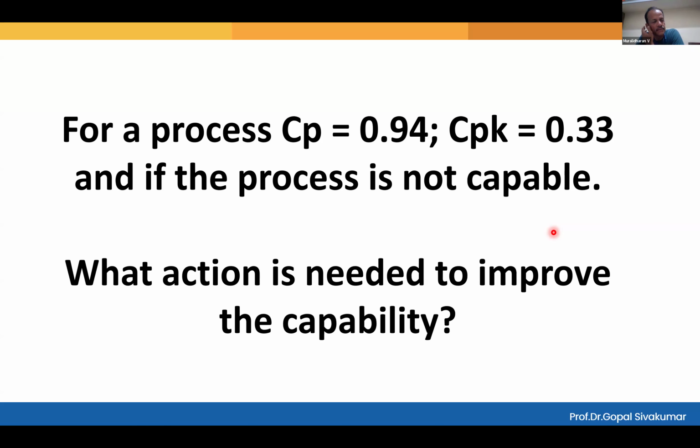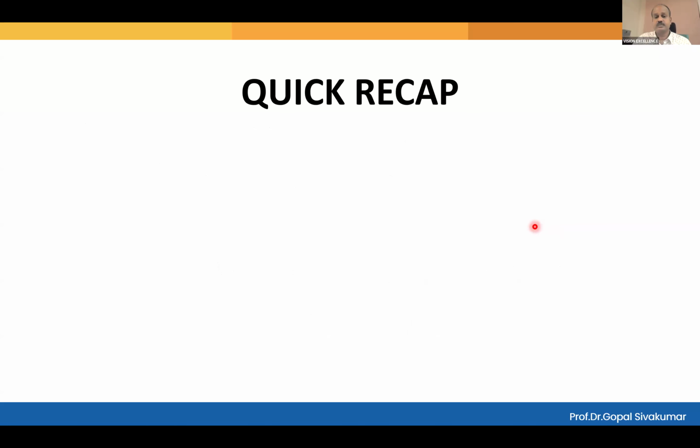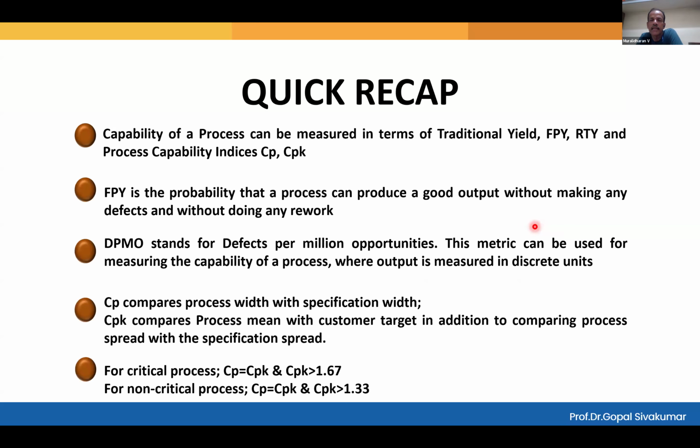Sir, one special case. In reality, processes like extrusion, die casting, pressing tools, the output part will be maintained initially at the lowest stage, so that over usage, it will compulsorily move to the higher side, and it will utilize the tool life for a longer time. In that case, if you maintain the mean at the center, then it's not economical. I am telling about the special case, not about machining. Are you getting my point, sir?